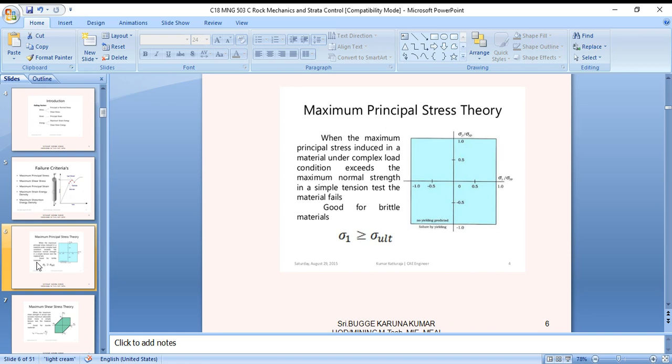The criteria for failure is specified as the mechanical condition under which a solid material fails by fracturing or by deforming beyond some specific limit. This specification may be in terms of the stresses, strain, rate of change of stress, rate of change of strain, or some combination of these quantities in the material, because materials are tested under a mechanical condition equivalent to that which they will experience in service. It is necessary for engineering purposes to have a valid criteria of failure.